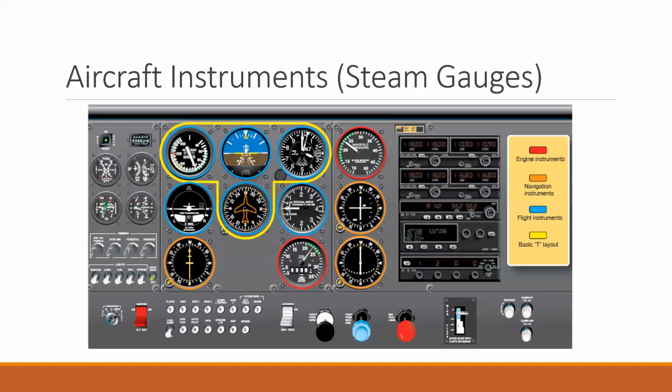There are some other extraneous instruments on here. Like to the right of the altitude indicator, you have a manifold pressure indicator, which, since this is a constant speed propeller aircraft, is helpful in determining blade angle.